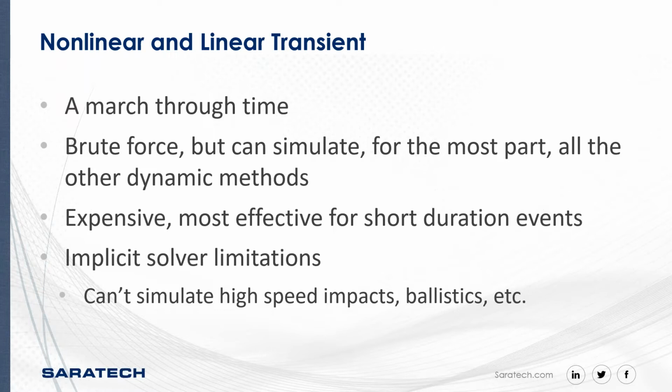But also something to keep in mind is that even though this is transient and we're looking at transient situations, it can't simulate very fast occurring situations because we are limited by that of the implicit solver. So things like a high-speed impact or ballistics are going to exceed the limitations of our transient analysis.